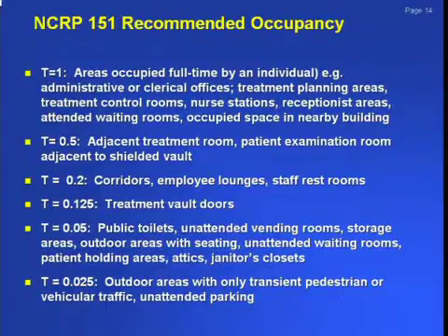And that goes for basically vending rooms, outdoor areas with seating, unattended waiting rooms, anywhere it's basically just where someone may come in and go out, your janitor closet, typical areas like that. For outdoor areas, we assume the occupancy is 0.025, and that is the number you can use for an unattended parking lot. What you have to be very careful is that that doesn't become a paid attendant parking lot, so that you don't have a parking attendant now sitting right under your linear accelerator beam.